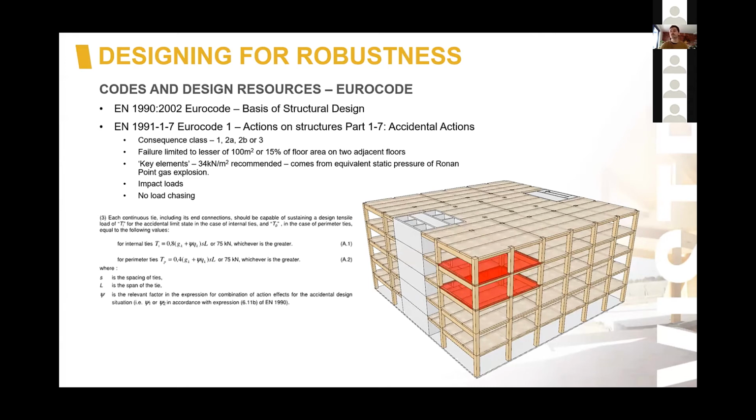and that would be considered within the disproportionate collapse criteria. Then looking at key elements, the recommended pressure to be used is 34 kPa, or kilonewtons per square metre, and this actually comes from the Ronan Point gas explosion. The post failure investigation determined that the equivalent static pressure would be 34 kPa. So that's why that example is used so commonly and is so relevant for robustness, because it really influences the key element design in the Eurocode.